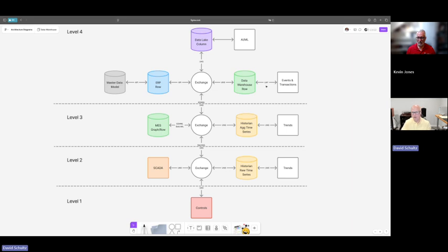So we're coming all the way full circle to the master data model. That unified analytics framework gives me the ability to get at aggregated data, contextualized data, that's also going to have some events and some transaction type information there. So a classic example is, what was my maximum temperature during this particular batch operation? Or, what were the times at the beginning and the end of this downtime event that existed within a manufacturing process? So what this allows you to do is take a lot of this information and look at it together, but it becomes row-based, very easy to query.